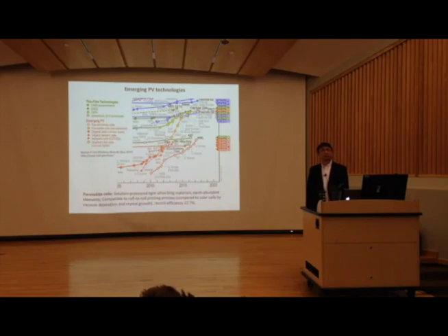Well, what is happening with some of those discussions is that some of the fire departments, I think this is the case in Calgary, are basically saying that they don't vent residential buildings anymore, because the glulams and such go up in flames so fast that they can't really trust getting up on the roof. So for them, it's not a big issue in terms of needing to ventilate on the roof space. Other fire departments have a different view on that, so it's an ongoing discussion, really.